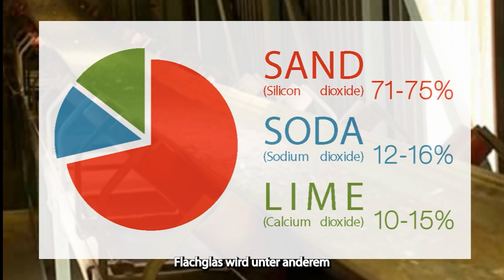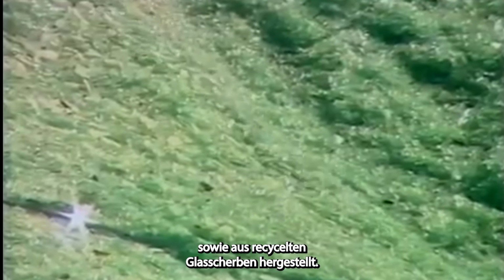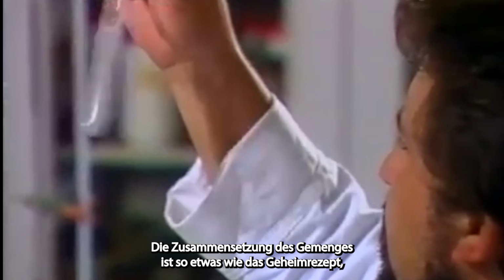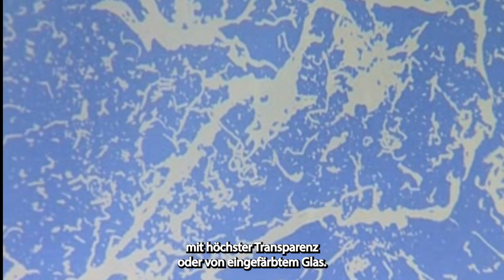Flat glass is made of abundant raw materials like sand and soda ash, as well as from recycled broken glass, also known as cullet. The raw materials mixture for glass melting is known as the batch. The batch formulation is like the magic recipe to obtain the desired glass. The exact formulation will vary when producing glass with the highest transparency or colored glass.